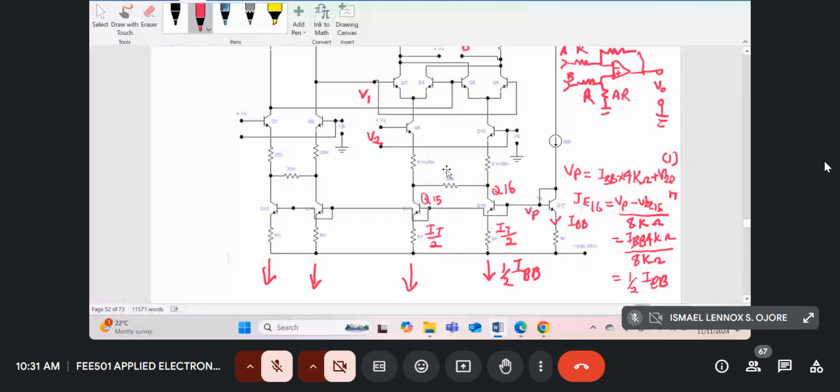Excuse me, sir. Yes. I wish to seek a clarification concerning the calculation for IE16. Would the negative voltage, the minus VEE, affect that calculation, or do we just use the emitter voltage alone? No, the negative does not come into play. But if you want to use it, you can use it. It doesn't matter. You can start from minus VEE plus VBE of Q17, right? But since I'm using minus VEE as a common reference, I know it's negative. So the drop from minus VEE to the emitter of Q17 would be IBB times 4K.